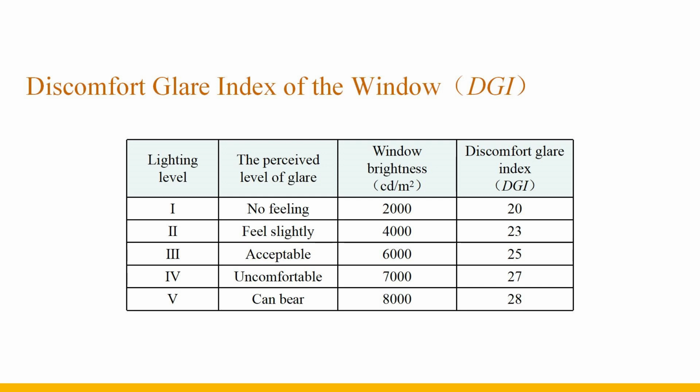First, the working area should reduce or avoid direct sunlight exposure. Second, it is not advisable to use a bright window as a viewing background. Third, indoor and outdoor shading can be used to reduce the brightness of window openings or reduce the revealing solid angle of the sky. Fourth, it is recommended to make the inner surface of the window structure or the inner wall around the window a light-colored finish.